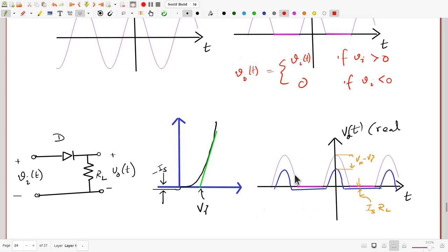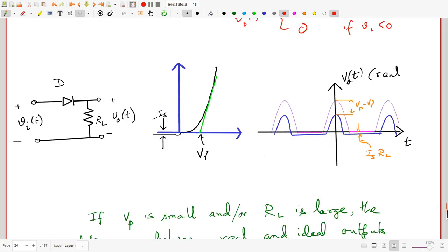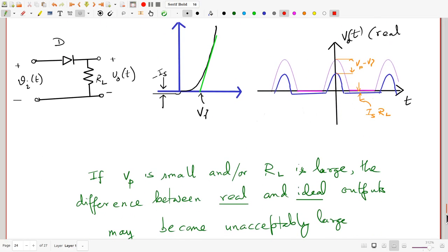However, you can often use rectifiers not for power supply purposes, but for some precision calculations maybe, or figuring out some precision data dealing with an input signal. And in such cases, the input voltage peak or the currents involved may not be so huge that we can ignore these deviations. So, for high precision applications, these deviations from non-ideality are sometimes unacceptably large.